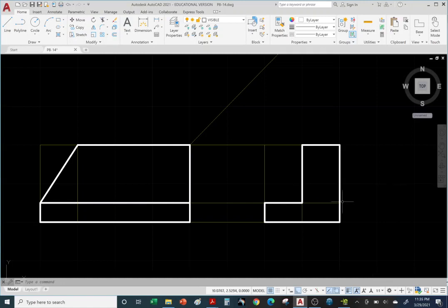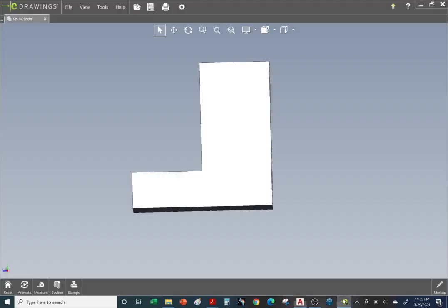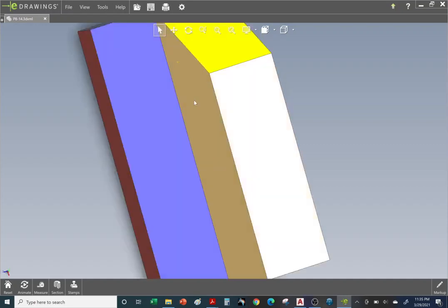Now we need the red hidden line, right? So now we don't draw a red hidden line here because we have the solid visible object line in front that's overlapping and overriding it. For this case here, we don't have an object line, so we do need to draw that red hidden line to represent the one on the opposite side.